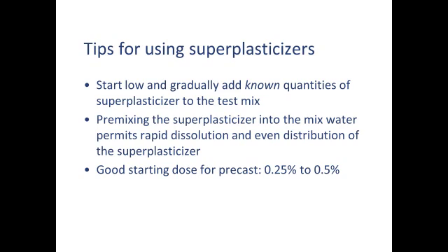If you go back to a few slides where I said admixtures are added by weight of dry ingredients, I gave the example of 2%. Well, this is 0.25%, 1/4%, or 1/4 of a kilo for every 100 kilos. So a percent is 1 per 100. 1/4% is 1/4 per 100. That's what that means.